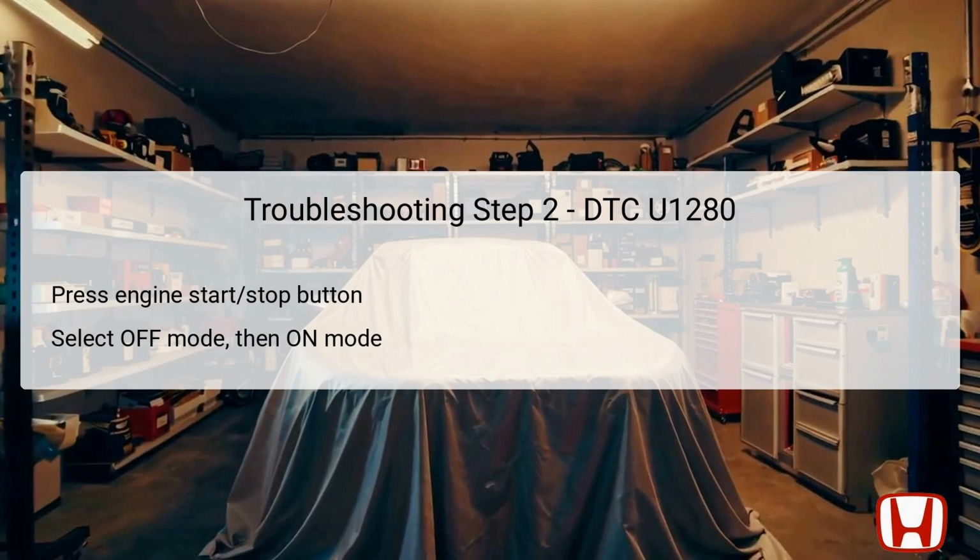Following the DTC clearance, the technician needs to press the engine start-stop button to toggle through the off and then on modes. This step is crucial as it allows the vehicle's systems to initialize correctly. Putting the vehicle in off mode and then back to on essentially wakes up the electronics, providing a chance for the control units to perform self-checks.